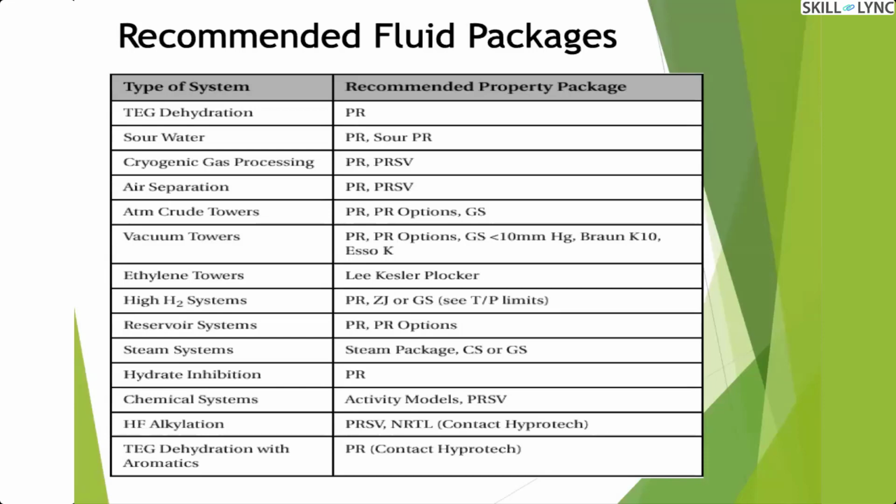Each of the fluid packages will have a different set of vapor liquid equilibrium data, which we call VLE data. As I've said in the earlier slides, if you have to see how much is your liquid content or how much is your vapor content in the pipe, that is all dependent on your vapor liquid equilibrium data, which is VLE data. So that VLE data is specific for each of the property packages.